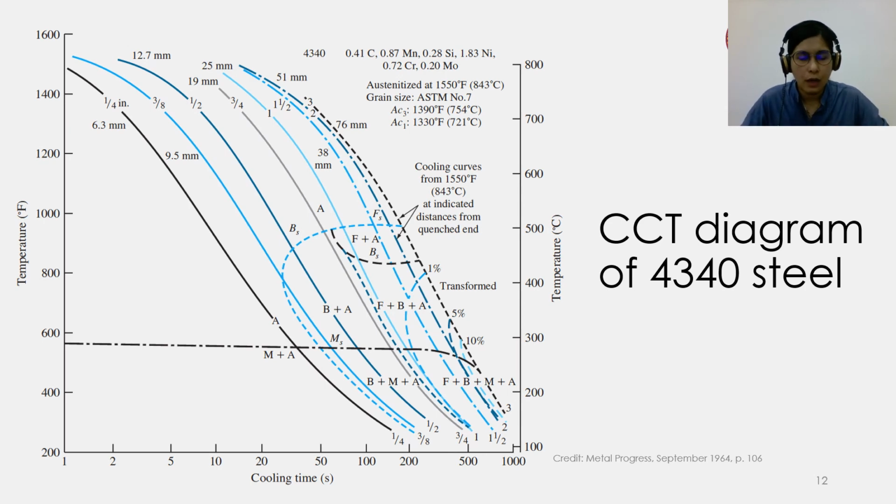And also different from the eutectoid steel just now, that consists only of carbon and iron with a percentage of 0.8 percent. You can observe here that with different alloying elements being added to the steel, and with the amount of carbon at different percentages, bainite starts to transform as well. So this is just an example.